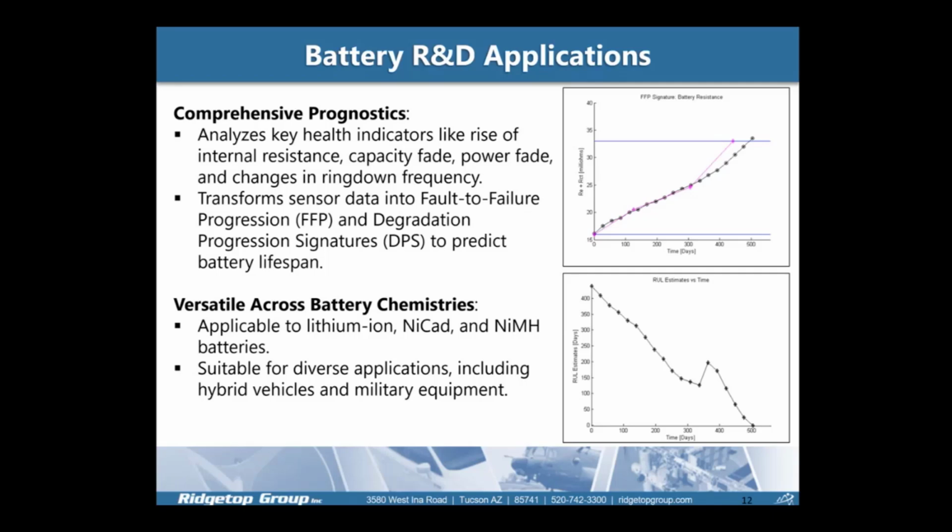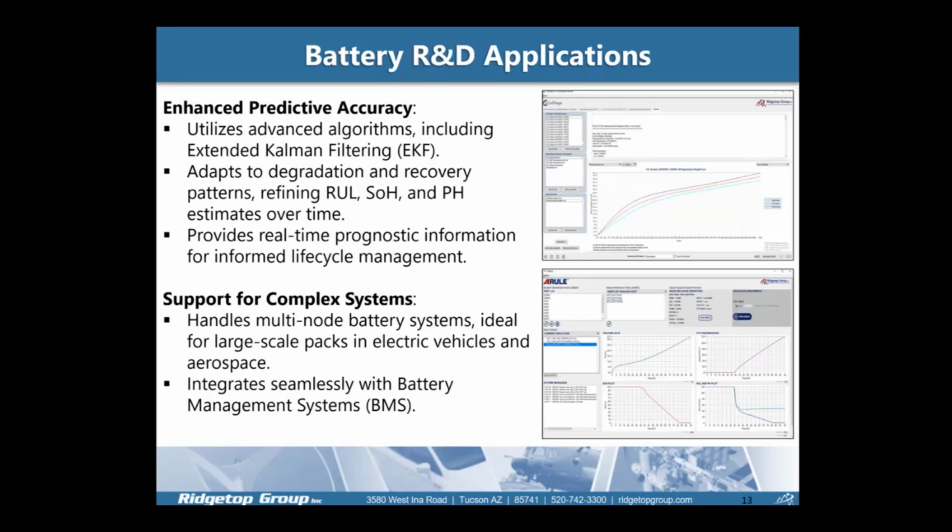And on this slide, we can see another example where we're looking at the best case, average case, and worst case capacity loss that is simulated from one of our battery health modeling and simulation tools called CellSage. And we can define a functional failure threshold at approximately 20% of a nominal capacity loss.